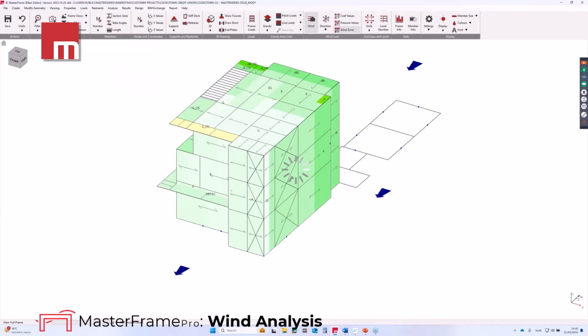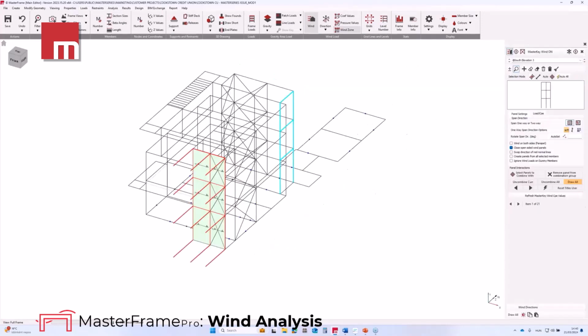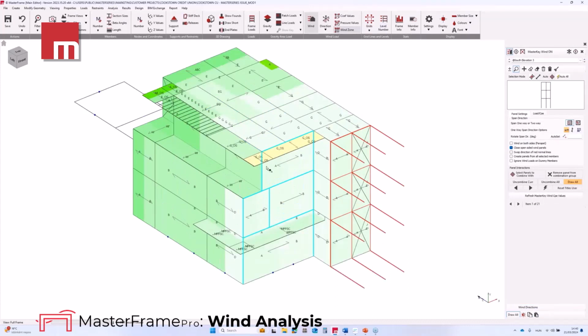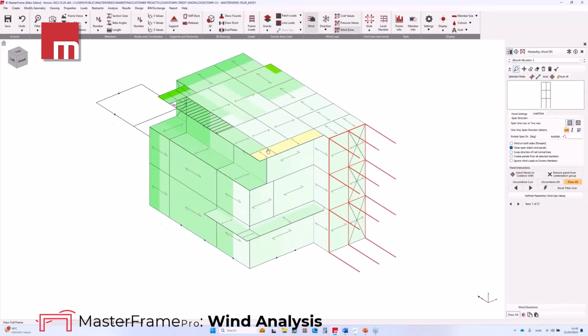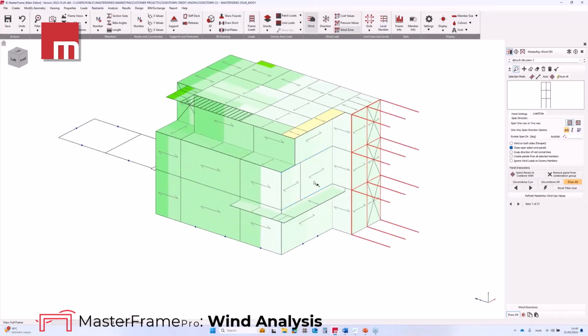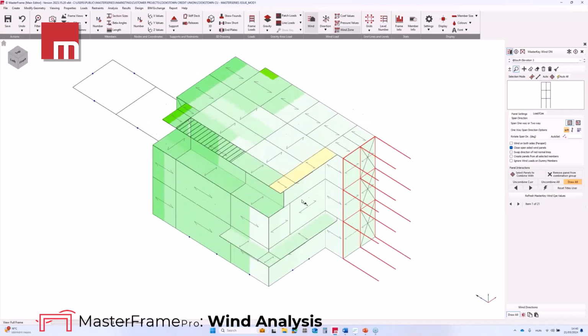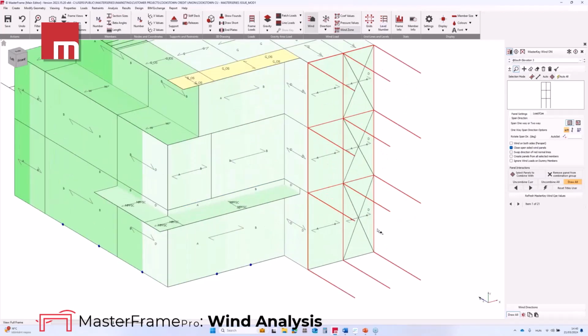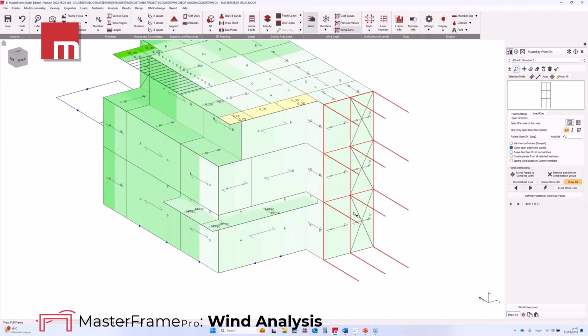Wind panels. So similar to the area loading, the wind loads are applied to panels, wind panels. The wall panels are horizontally spanning, while the roof panels span in the shorter direction. Bracing elements have a special bracing property on them, from which the program knows that even if they lie in the plane of a wind panel, these elements do not carry any loading from the wind load.